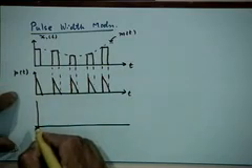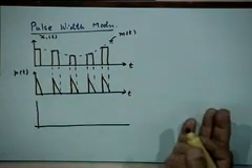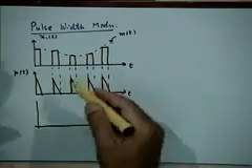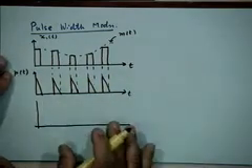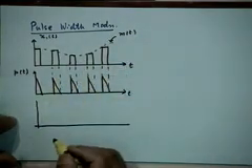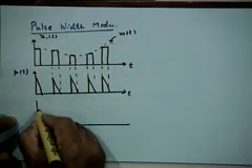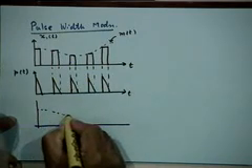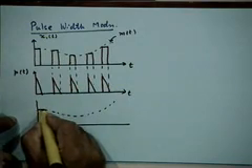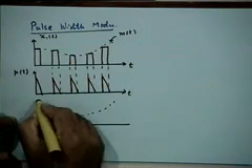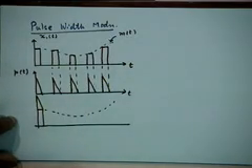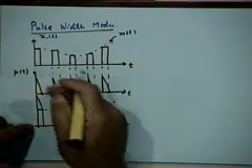So what is the amplitude of p(t)? Some constant amplitude. It is not important, suitably selected so as to satisfy practical requirements. Now you simply add up these two signals. So what will you see? Let me redraw that PAM signal. So on top of this pulse, you will get this triangular pulse, right? You added up these two, right?